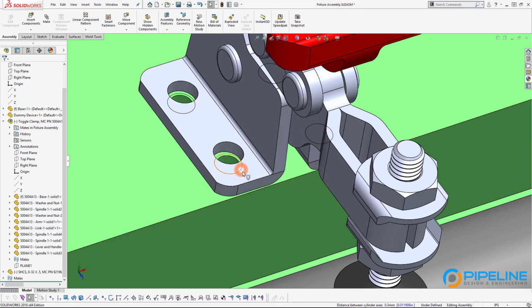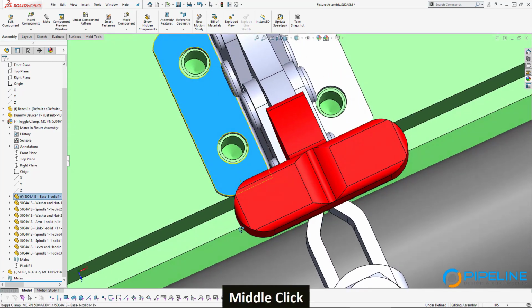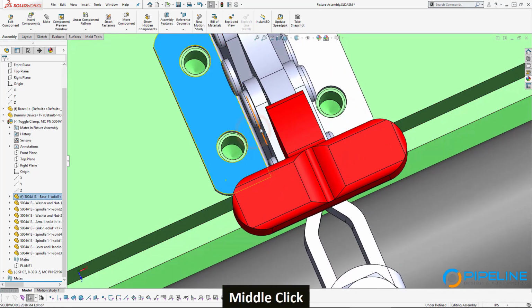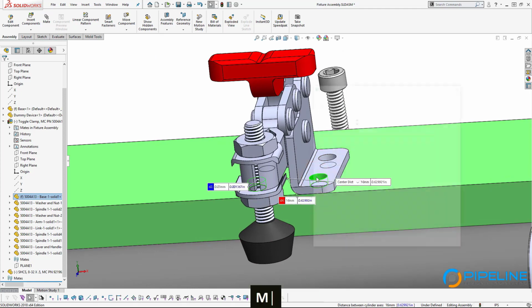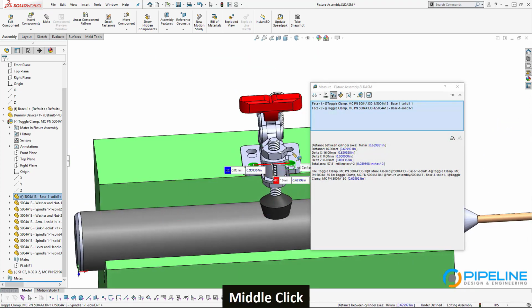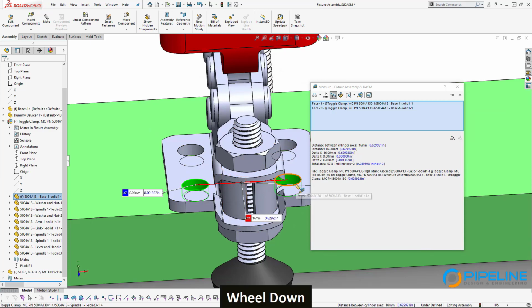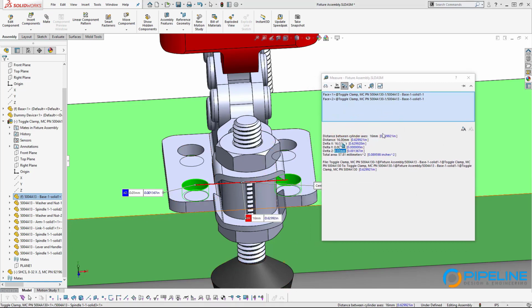One thing you might find is that stuff might look really close to being the same dimension, but if it's not exactly the same dimension, SolidWorks won't like it. So if we just look at the part, I can measure from one hole to the other by selecting both of the holes and then hitting the M key for measure. And that pops up just like this. You see this little window, shows you a whole bunch of information, and it draws stuff into the world here.